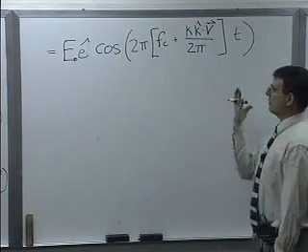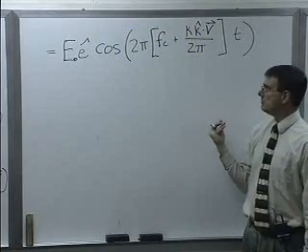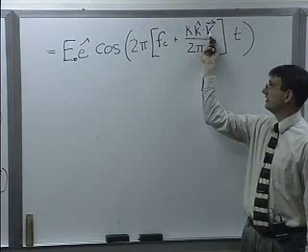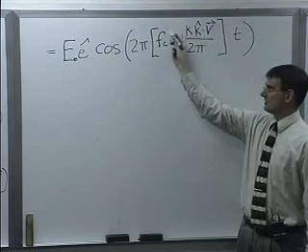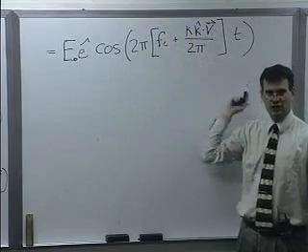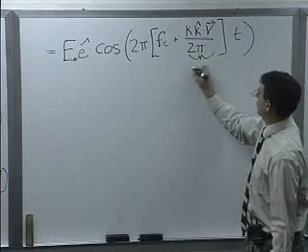And so from my temporal perspective at my receiver, when I am in motion, when I have a non-zero velocity vector, it looks like my carrier frequency just changed. It shifted. And so we often call this term here the Doppler shift.